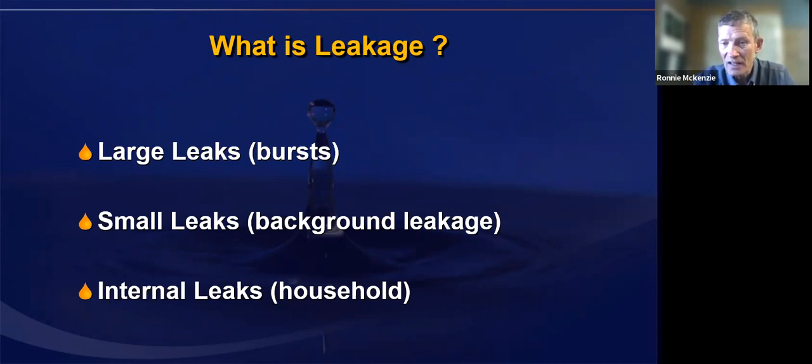That's basically leakage in properties through the taps, showers and toilets, where the residents are supplied with water on a continuous basis, but in many cases they don't have the financial means to maintain their pipework within the properties. As a result, we have some very high internal plumbing leakage, which can often be in the order of 80%. So it can be quite significant.